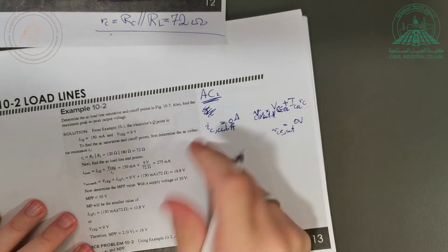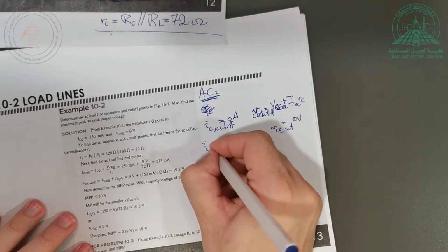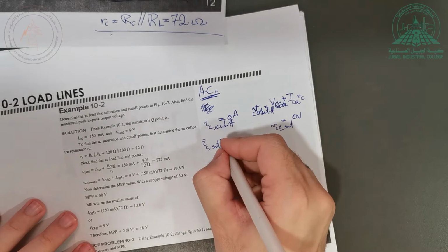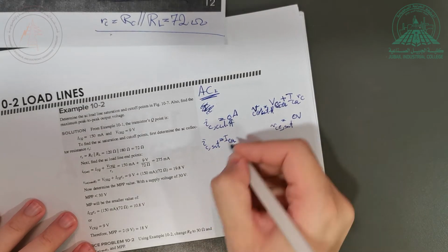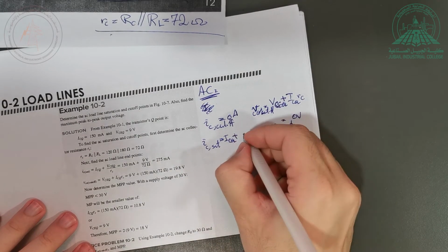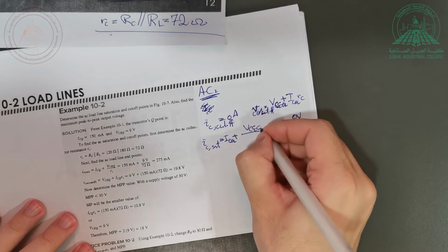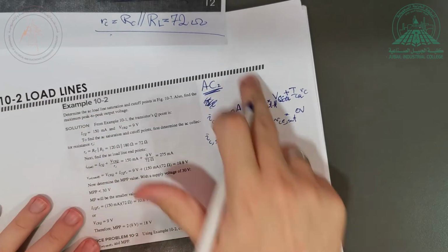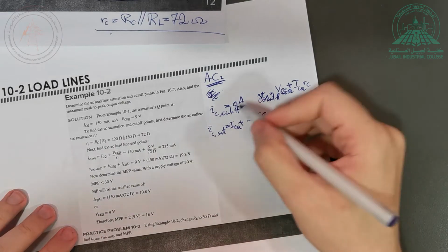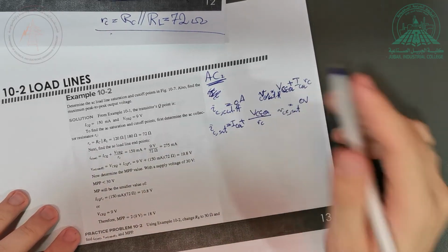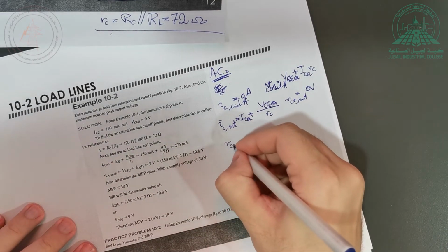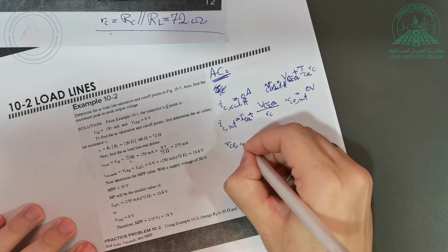How about iC in the case of saturation? Same thing, start with ICQ, then we add to it, applying Ohm's law, VCEQ divided by RC. Okay, this is 0, this is 0, and I have to get this, so we can say that VCE cutoff